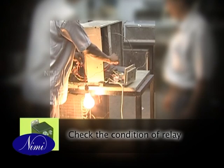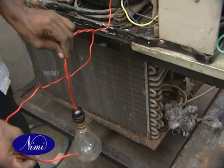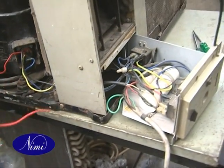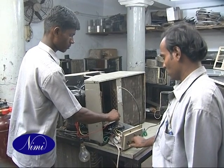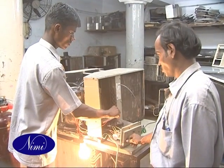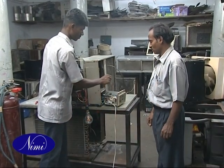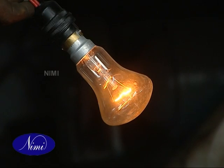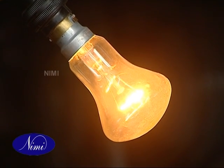Check the condition of the relay. Connect the test lamp to number 5 on the relay and S, that is the start winding, to the compressor before switching to cool. Observe the light. It will give a less glow. If the compressor does not start, check for other electrical defects.